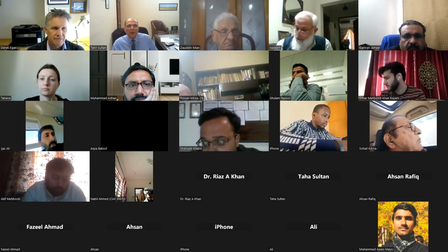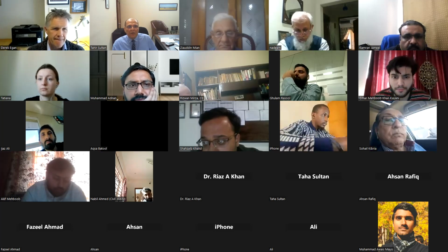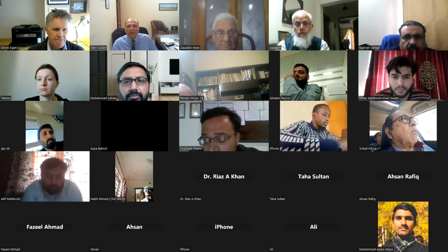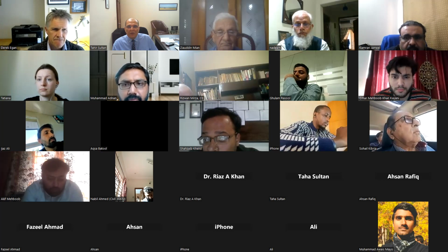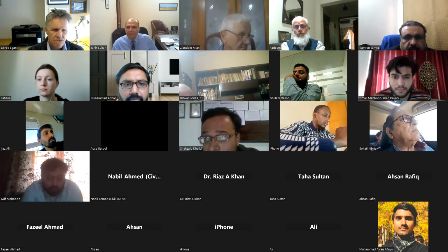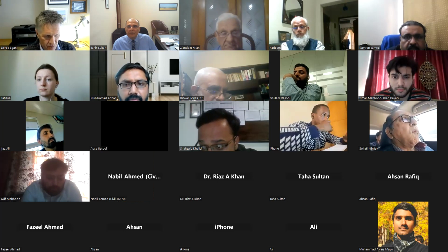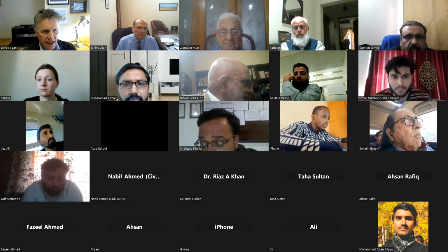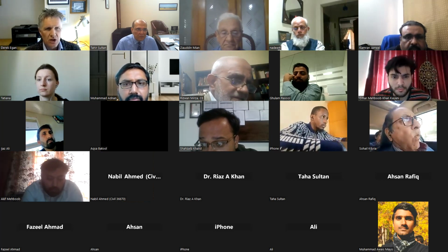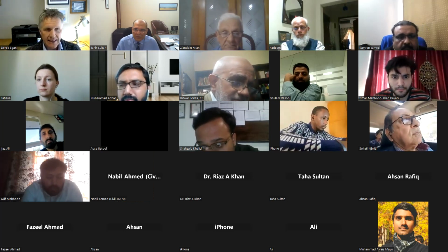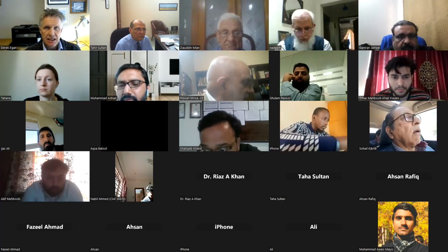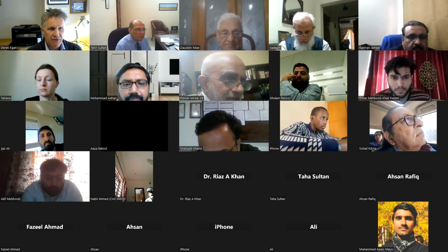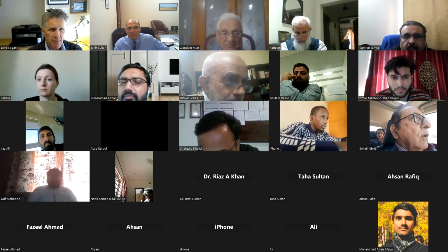Okay. Now we have a question from Nabil Ahmed. He's asking, how effective is the rigid inclusion system in order to mitigate the soil susceptible to liquefaction? You can use them for liquefaction or seismic situations, but you've got to be very, very careful in your design that they don't break, because they're quite brittle.